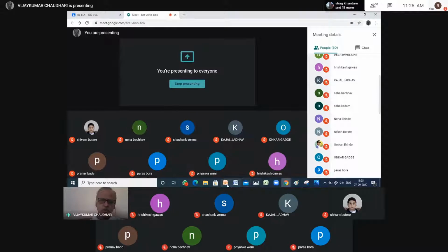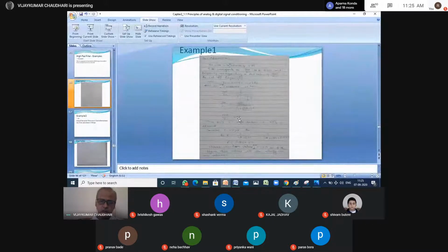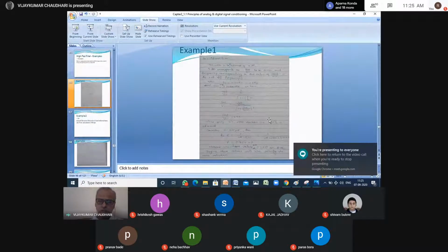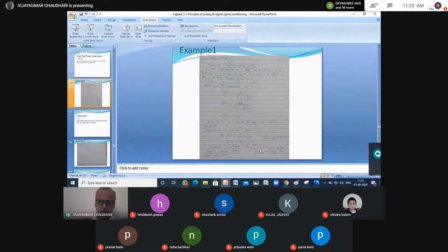What I want to check is whether this satisfies this criteria or not. This criteria 0.03. For this FC and for this FC, if I choose this or choose this, whether this criteria is satisfied or not. 97% reduction and 3% noise remaining. Otherwise, I have to choose exactly this value using a potentiometer also.